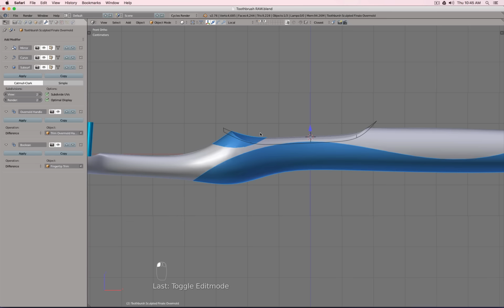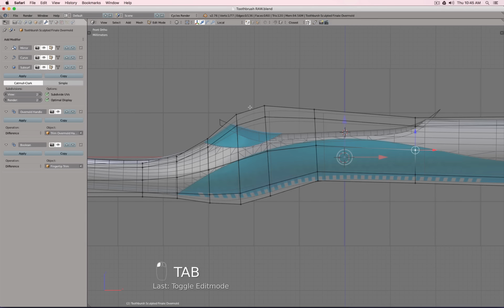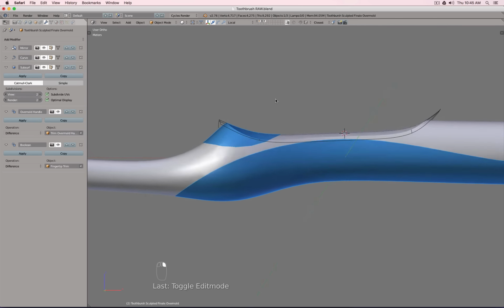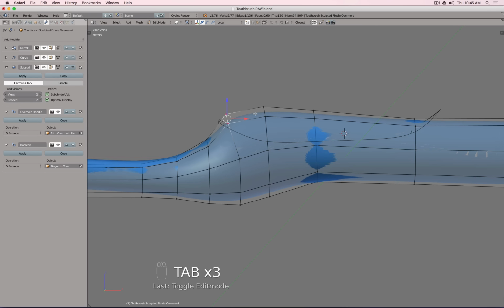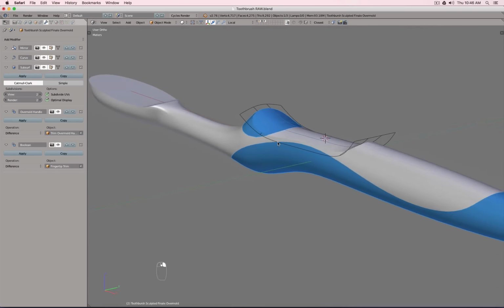And 2. Now, if, for example, I would like to change this one to come a little bit more forward, I could select whatever object I want. And for example, here, select all this, move it to there. Obviously, I have to move it so it still sits in there. And you see then each object has exactly the same change applied to it because they share the same mesh. And then when I split everything, those two parts perfectly fit because the white part is carved out of the same geometry as the blue part.